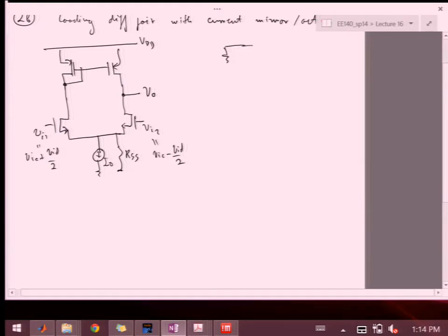Before I do that, if we just looked at this circuit, maybe I can ground this node over here. If I do certain approximations, if I forget the ROs of these two devices and ground it, then differentially, this voltage over here is mapped to this node through its gm and whatever the total resistance is here. That resistance is pretty high. It's the RO of this device and this device.